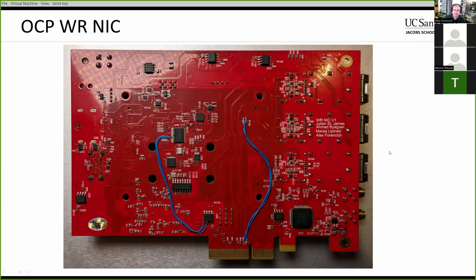the board. I guess I had to make a few other changes as well. There were some jumpers that had to be connected, and then I think I had to remove one or two termination resistors as well. And then also there was a minor fab problem. The little voltage regulator here was backwards, and that prevented the FTDI chip from working. So, interesting thing is, the regulator was actually fine. I turned it around and it just worked.